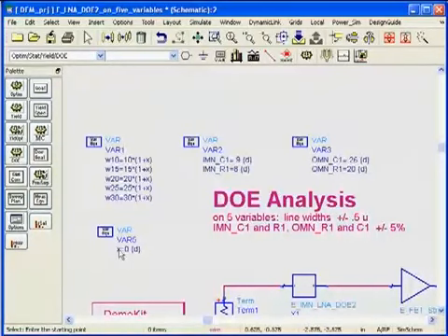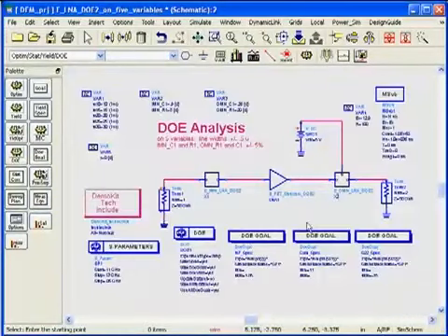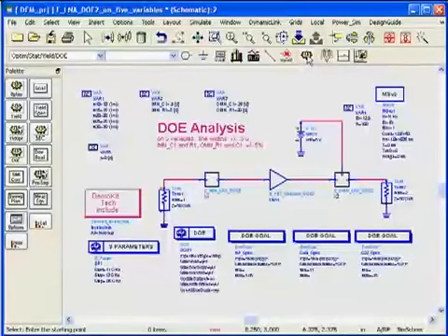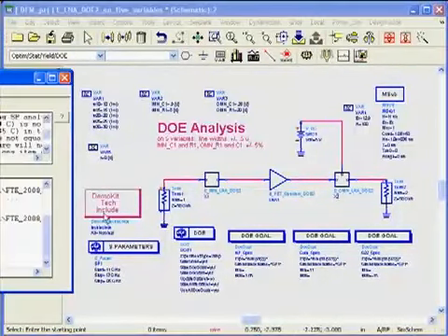And notice here x varies in the DOE, minus 0.05 to plus 0.05. So this way, this variable controls all the width of the line together, plus or minus 0.05 for this equation. So I have 5 variables now, and all I have to do, I have the setup here, all I have to do is just simulate. And notice when the simulation runs, it produces 32 experiments.